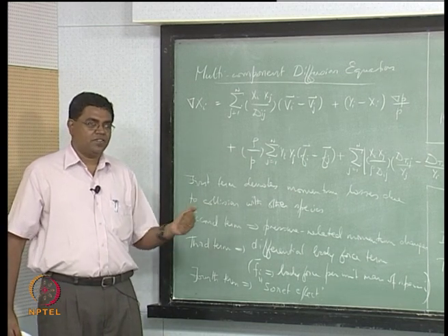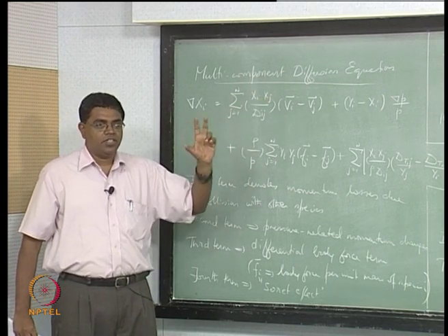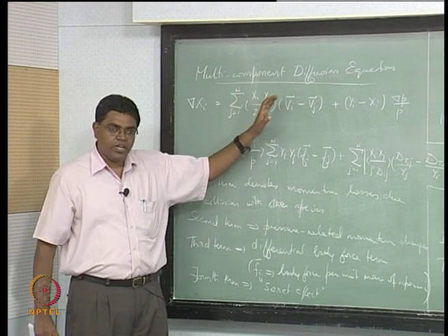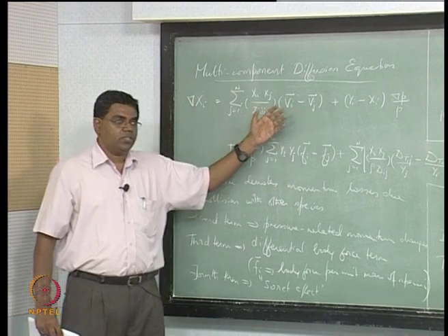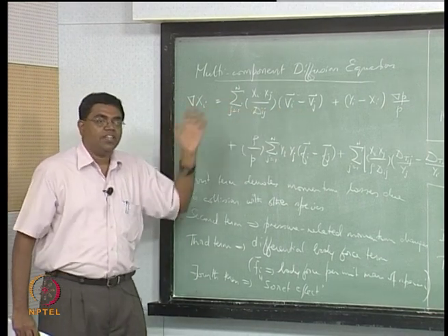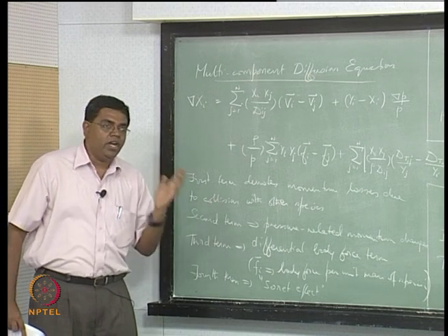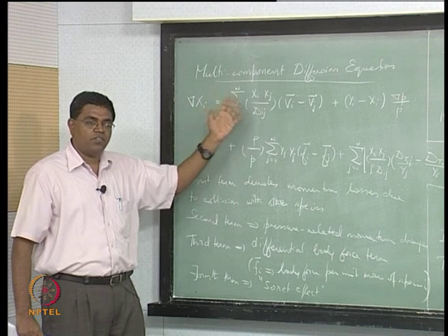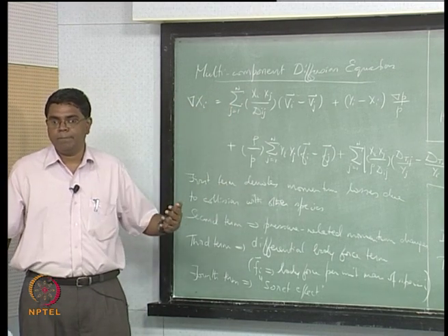But for the diffusion coefficient, we have to think about a pair of species at a time. That makes things complicated. We will try to work around it by some assumptions and simplifications a little later, but at the moment I have to point out that's how the process is. Mixing always involves a minimum of 2 species at a time, and we can always look at it as a process that involves 2 species at a time, even in a bunch of species together.